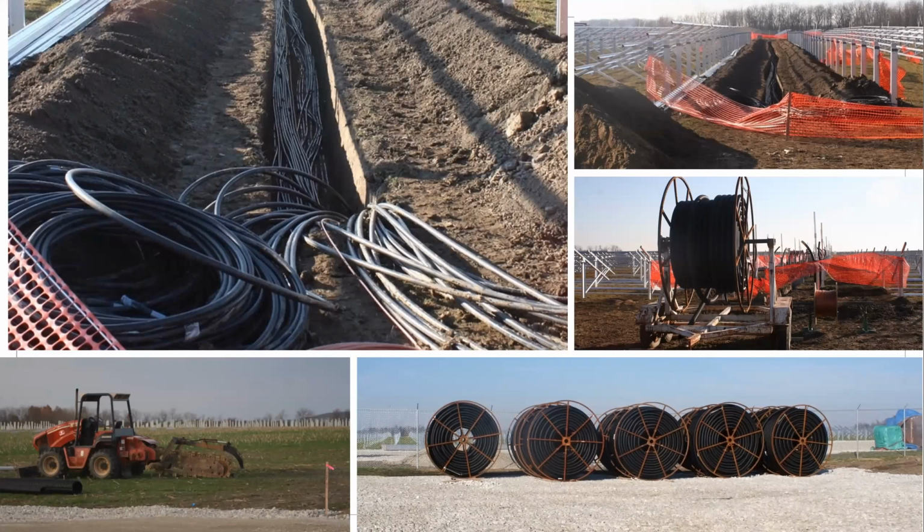I'm not sure, John can speak a little bit to how that impacts Nebraska, but in general, think about subsurface infrastructure as you think about the amount of trenching and posts that are going to be driven into the ground. Most of the decommissioning plans that I've come across here in Ohio read to where they plan to leave the cable. They basically say that the collectors are buried typically between 3 and 4 feet, and that they're not going to be removed during the decommissioning process. So that's something to consider.